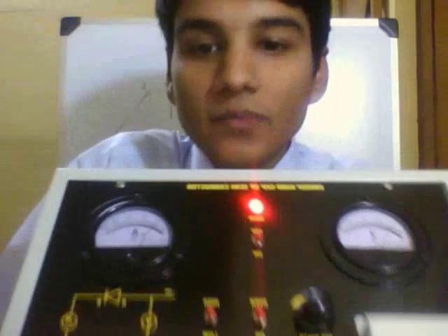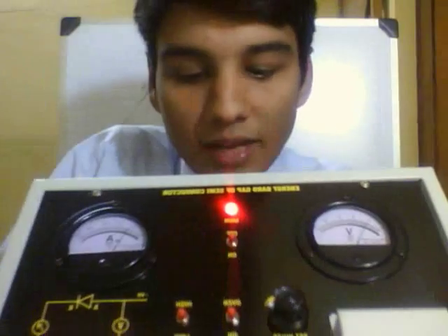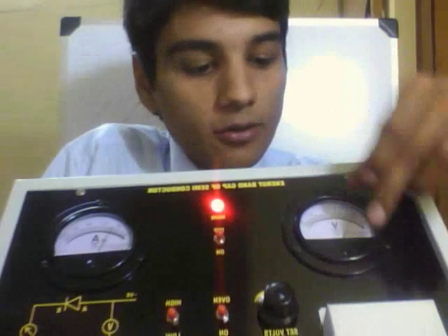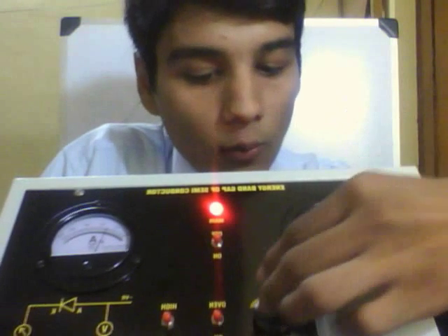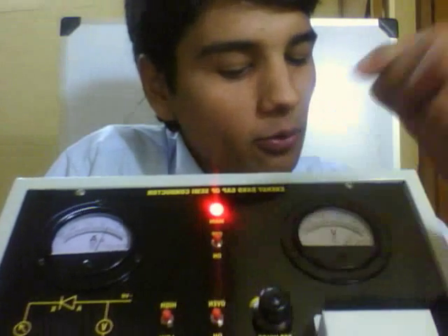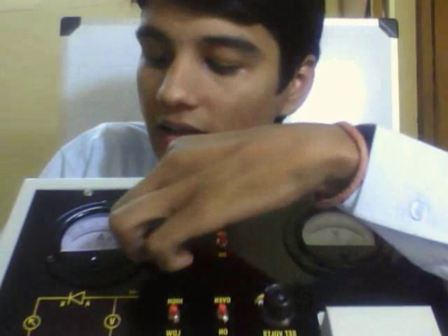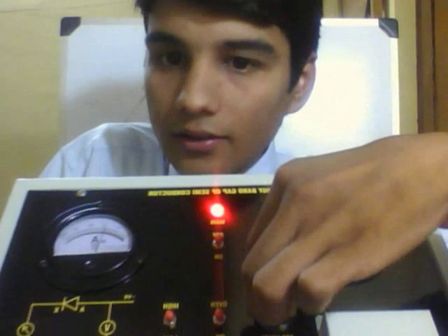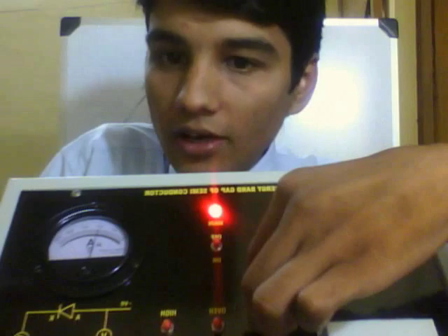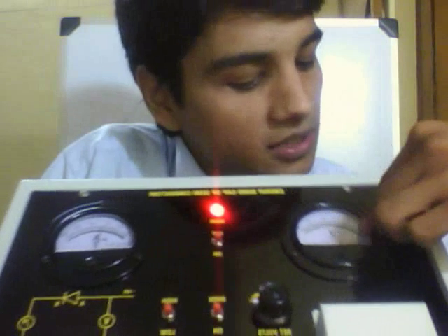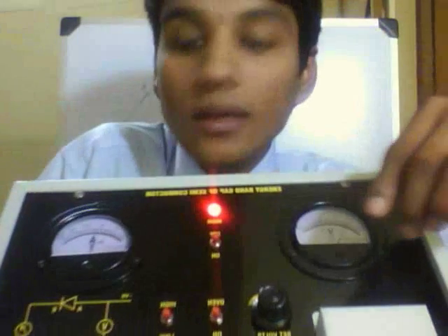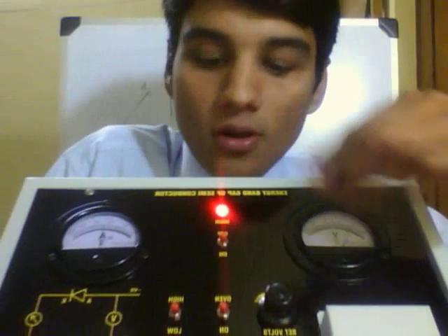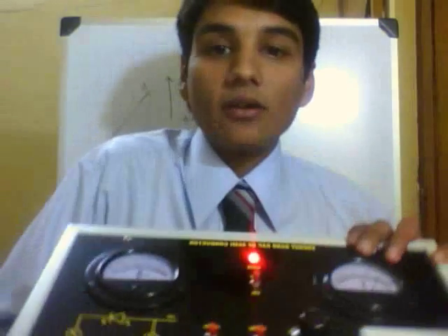So this is how the energy band gap is calculated. For a minimum change in voltage, the value of current changes very rapidly. Look at this. The value of current changes very rapidly as the voltage is increased from about 0 to 2 volts. The value of current changes by about 50 microamperes. Taking all this calculation, we will plot a graph on graph paper.